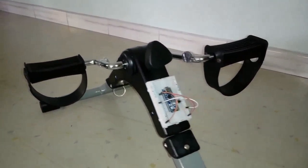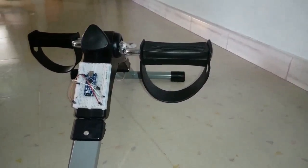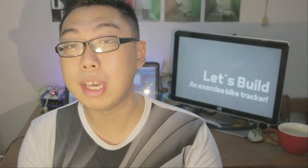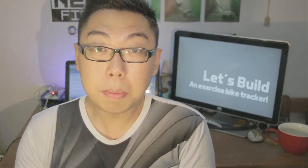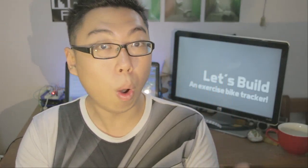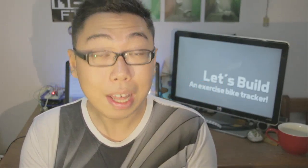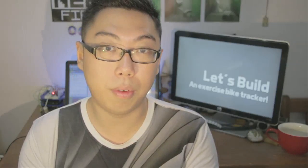It talks to some sensors, it picks up the position of the pedals, and at intervals, it shoots out messages via serial, which of course is communicating over USB. These messages are listened to by a program on the computer, which can then do things like generate a GUI or send keystrokes to something like Google Street View. That basically is the long and short of it all.